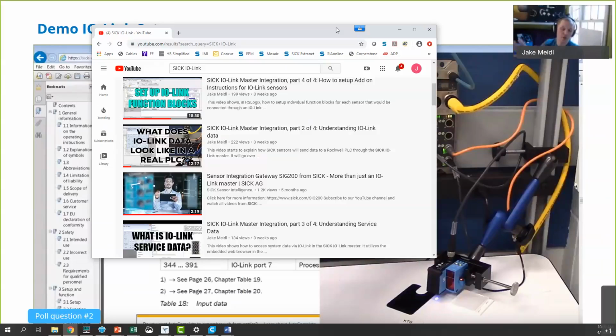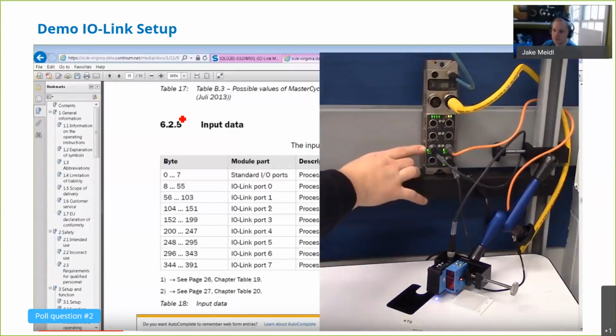information. So what we're looking at here is, I'll show pictures on the right, and then normally we'll get to the RSLogix screen on the left here, but what we're looking at is one master. We've got a sensor plugged into this third port down here. It could be port 3 in your mind. Actually, our ports start numbering at 0, so it goes 0, 1, and 2. This is port 2. And the sensor that we're looking at is a KTS contrast sensor. That one's interesting because it can give you a color value. It doesn't just give you a yes or a no like a photo eye would. This one will give you, hey, I see something, yes, no, but also it's a number between 0 and 999. So it's a little bit more interesting than just a basic photo eye, and that's why we used it.